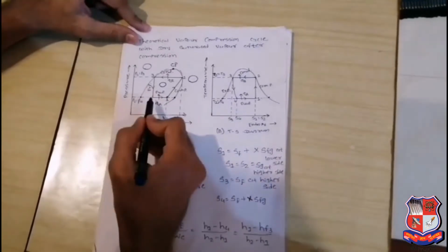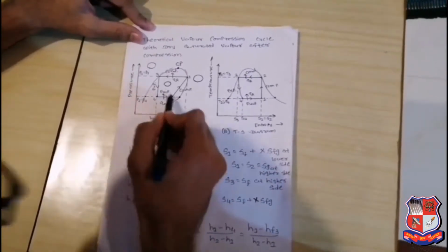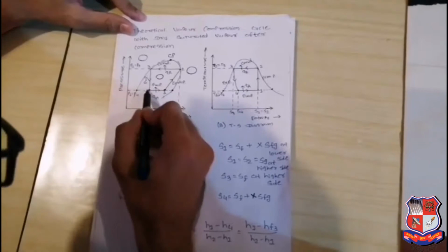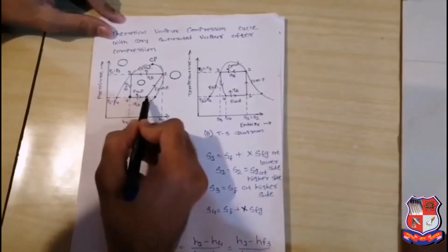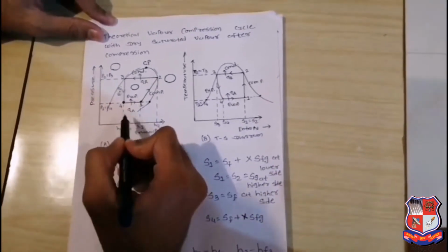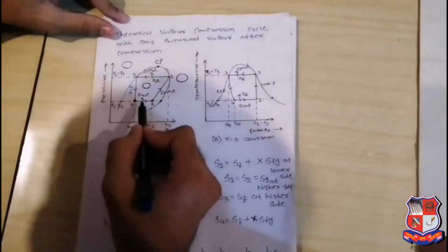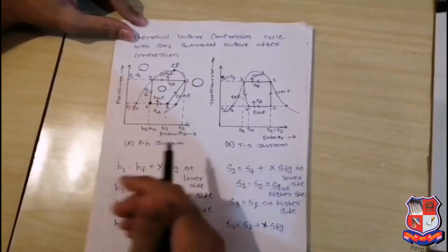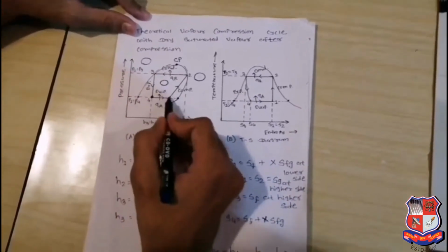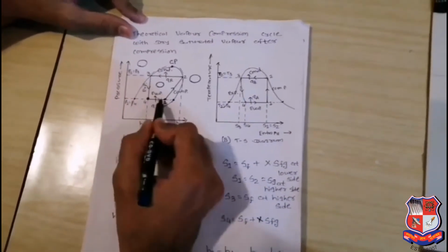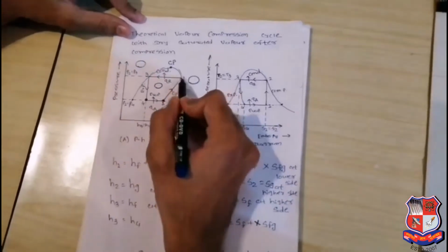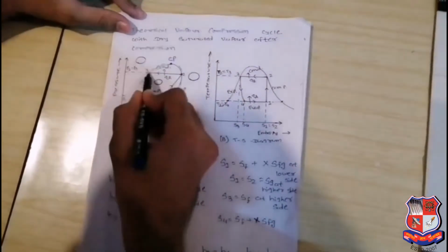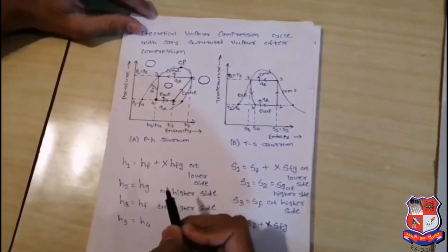So some amount of wet refrigerant is increasing, its temperature remains constant. During this process we are absorbing the heat from the cooling space. So at the time some amount of your enthalpy is increasing. At that time it becomes the first point. So at that time fourth and first point are in wet region, second point is dry saturated vapor, and third point is saturated liquid.